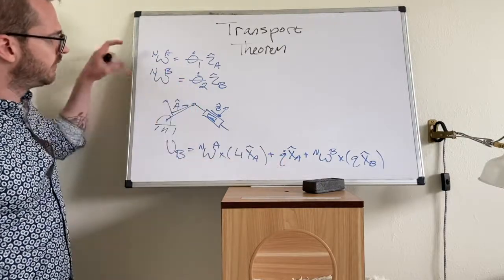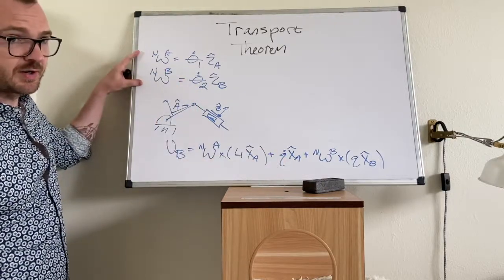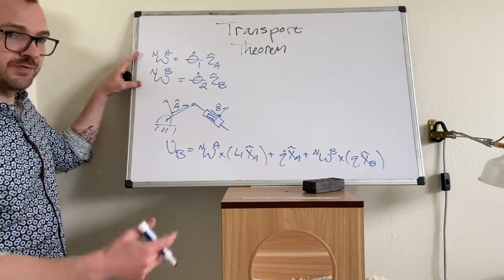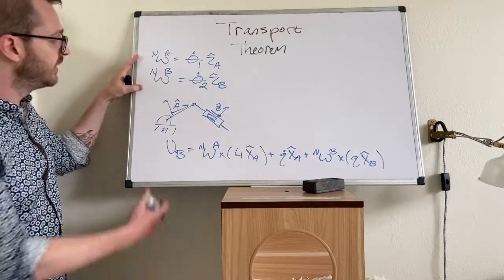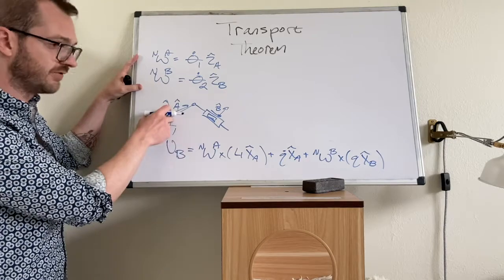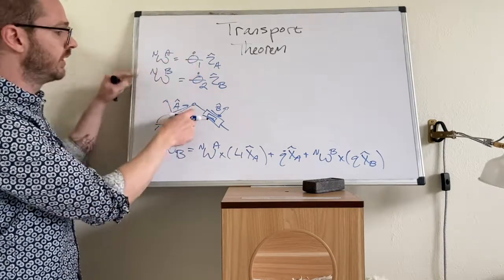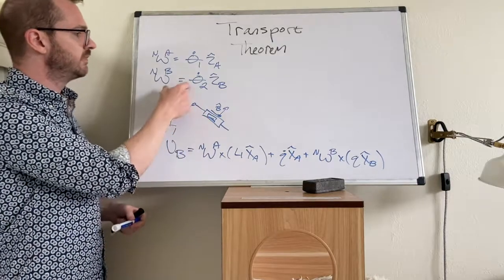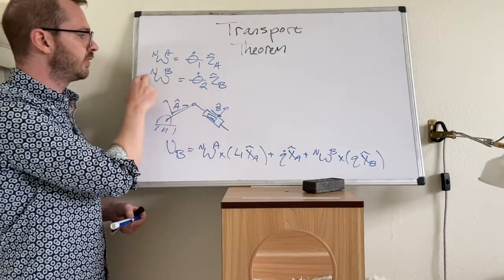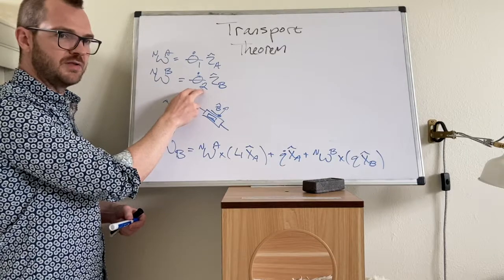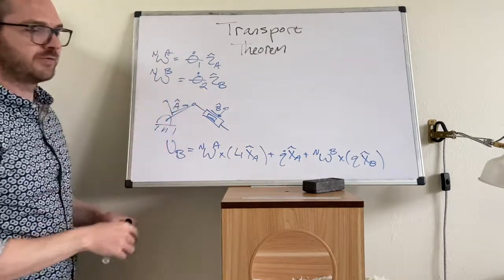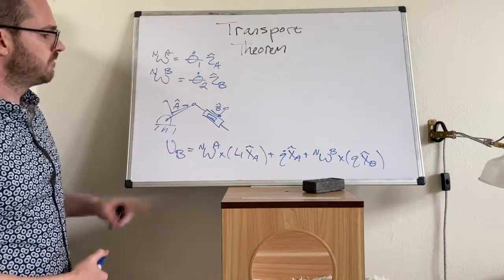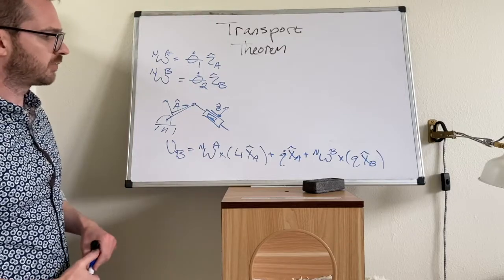All right, so again, I recommend you do angular velocities first. I think they're easy. You can do them from observation. Here's the A frame, it rotates with theta 1. Here's the B frame, it rotates with theta 2. And since in this problem, you can see how we define them, going from N to B is only the angle theta 2, that means this is an absolute angle. Okay, so we have to take care of these cross products.